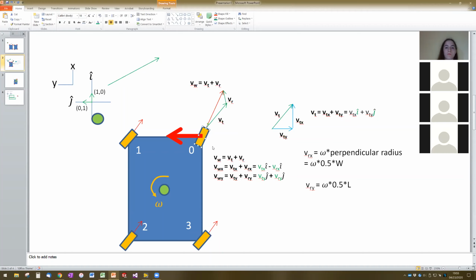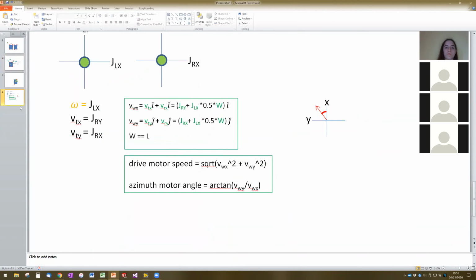And so when all of these vectors come into play, the rotation and translation that you will get from the robot physically will not be the rotation and translation that you asked it to get, because you're going to get capped by your maximum power, which is smaller than the maximum power that you're asking for on some of the wheel modules. Does anyone have any questions about that problem?